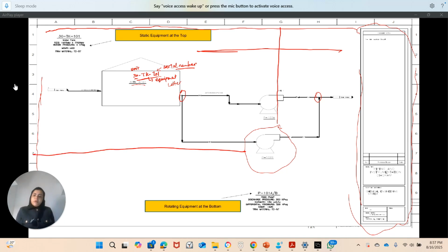So you say, okay, I want you to look into pump 102B, G7. So he knows that if he goes to this sheet and you tell him the information of the sheet, so let's say this sheet is sheet 100, and you say, okay, P&ID sheet 100, go to pump 102B, G7, and you state what is the actual issue, what you want him to do. So it helps you to aid understanding.